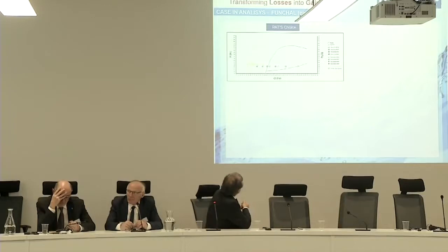With the reducing of the losses, the flow gets smaller in the other case. So the efficiency of the PAT is very important because we don't have, as in the transmission and supply systems, a constant flow. The flow is decreasing. So the high level of losses creates an opportunity, but is an enemy because it's turning the flow down.